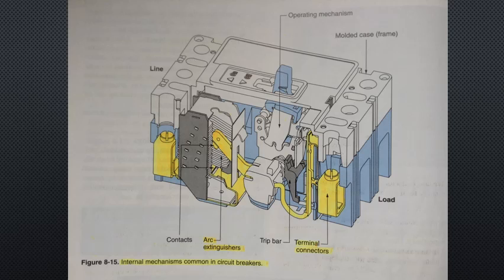The second type of circuit breaker is the inverse time circuit breaker. Like a dual element fuse, this circuit breaker has two mechanisms for sensing overloads. One mechanism allows for a certain amount of overload to occur. The other opens the circuit at a fault level current. An inverse time circuit breaker will allow as much as 10 times the overload current prior to opening the circuit.